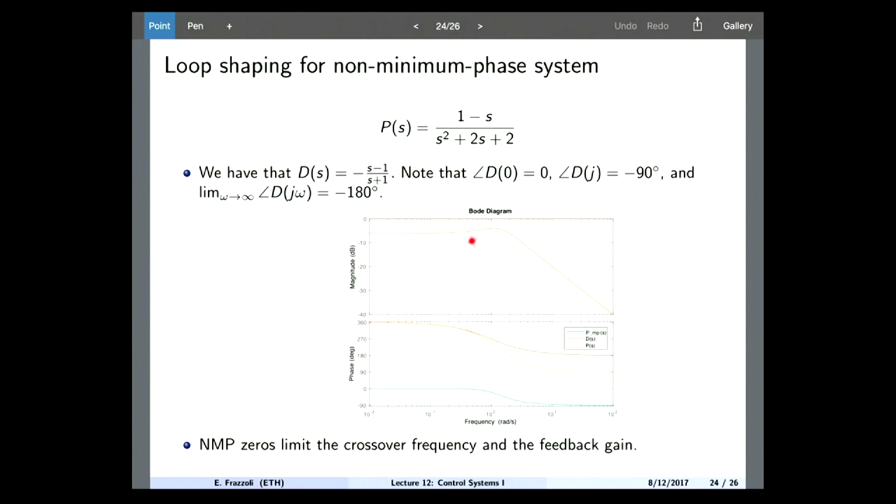Okay, so you see that the magnitude plot is not affected, okay? But look at, so the magnitude plot for my original transfer function is, what is it? Is the yellow line, the phase plot for my nice transfer function is the blue one. So you see that I may be led to believe, if I just look at the minimum phase one, that the maximum phase lag is actually negative 190 degrees.